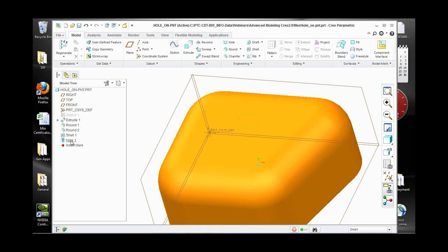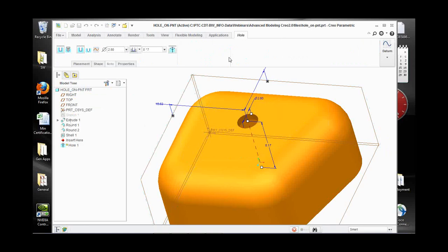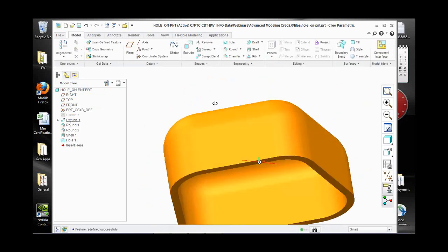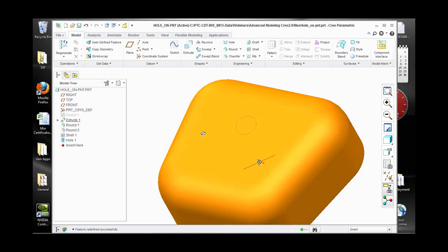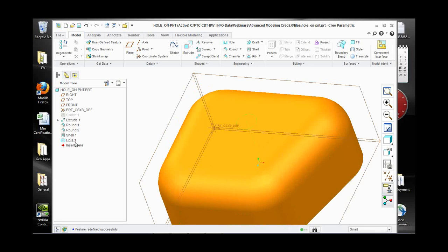So what this does is that instead of actually building the geometry, it puts the axis and an outline in there, and you can see this. You still can pattern that hole and copy that hole and do all your regular functions with it, but you're not actually creating the geometry. So as you are working on this model, the model regenerates, instead of regenerating all that geometry, it just regenerates essentially the sketch. And so in turn, your regeneration time decreases.